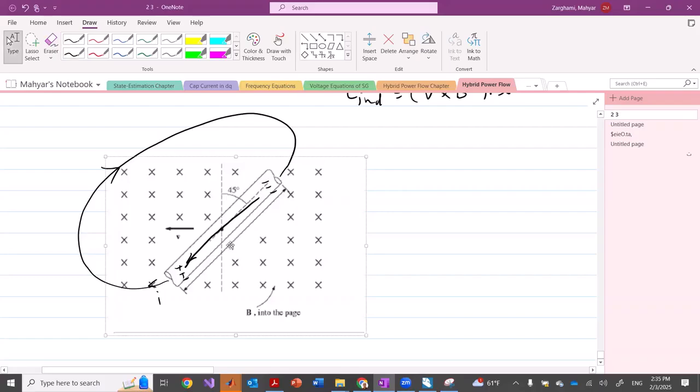Now, if you have this current in that direction, use the right-hand rule to determine the direction of the produced magnetic field. You see that it turns and wants to go out of the page, which is the opposite direction of the field that we have here. So that's correct: the positive polarity should be here, because it produces a current that tries to make a field going out of the page, as opposed to the field that right now is going into the page.